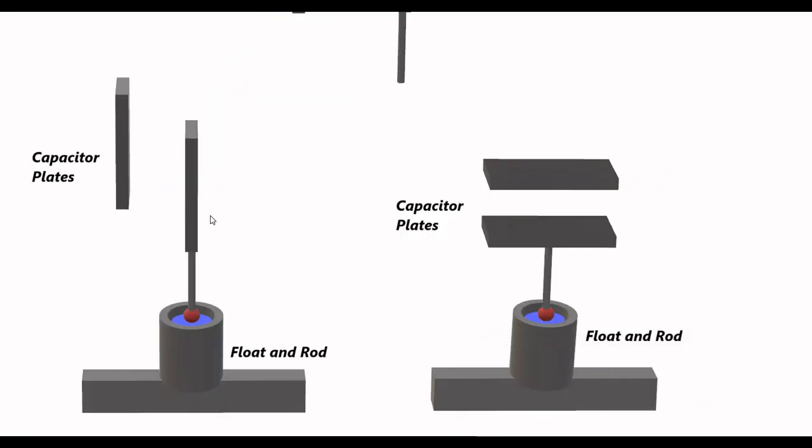Then we have the capacitive transducer, that has to measure the liquid level. So we have used a capacitive transducer. It can work either through change in overlapping area, change in separation distance, or change in permittivity, with the capacitive sensor plates connected across the walls of the container.